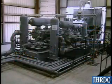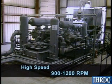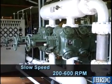Reciprocating compressors are classified as either high-speed or slow-speed. Typically, high-speed compressors run at a speed of 900 to 1200 RPM, whereas slow-speed compressors run at speeds of 200 to 600 RPM.